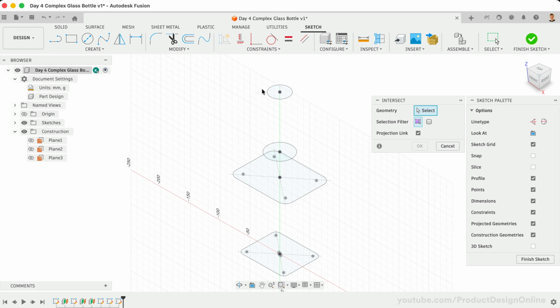By selecting this geometry to intersect, you create points on your active sketch plane exactly where the existing sketch passes through it. This allows you to guarantee that your guide rails connect to the 4 profiles. Select each of the 4 sketch profiles. The circles automatically intersect on both sides. However, you only need the left side of the rectangles since you will mirror the sketch geometry later.